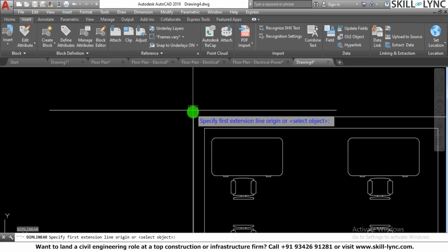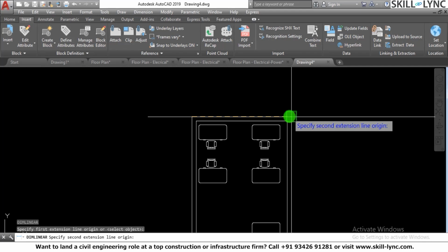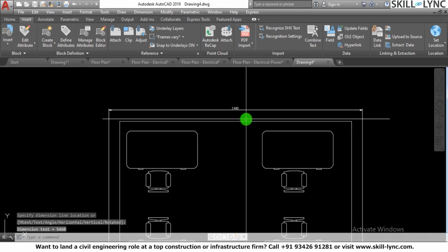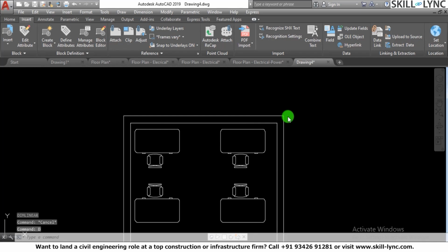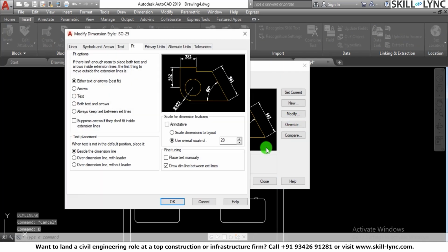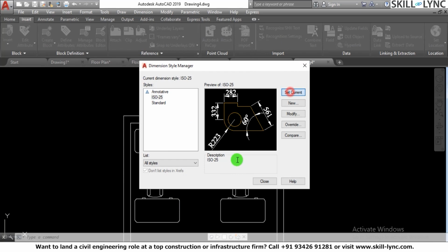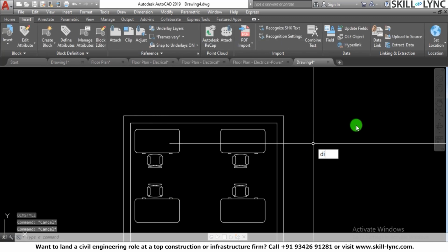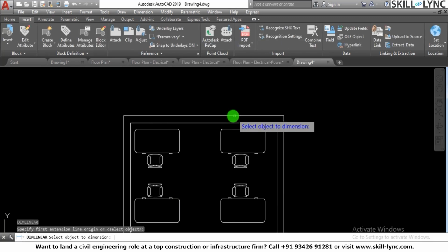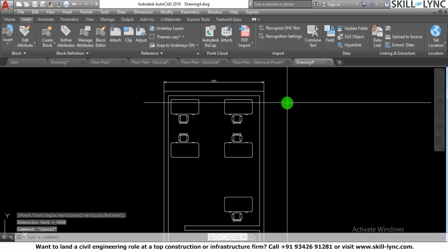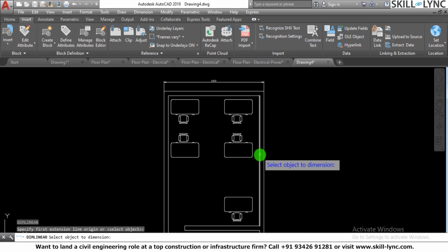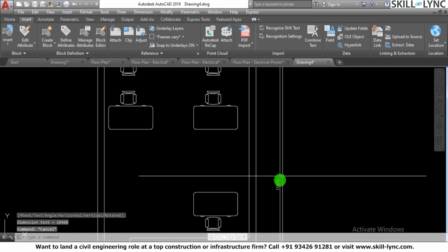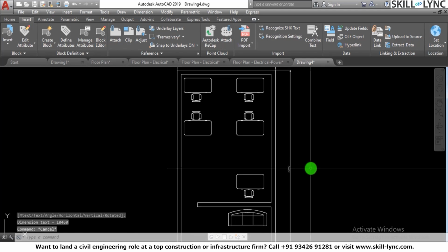In this drawing you have a workstation over here, with some blocks. Let me have the dimension. I can give a value, let's say 35, 40. That's a standard scale that I would be using for dim-lin. With quick dimensioning, I select the object, press enter and select this. Now you can see this is in millimeters.